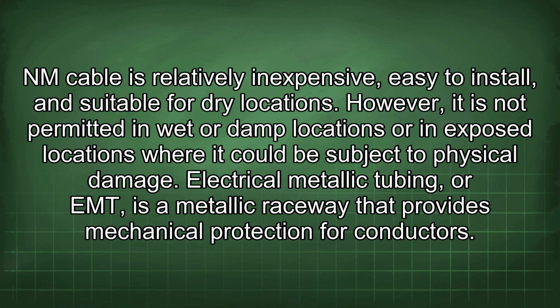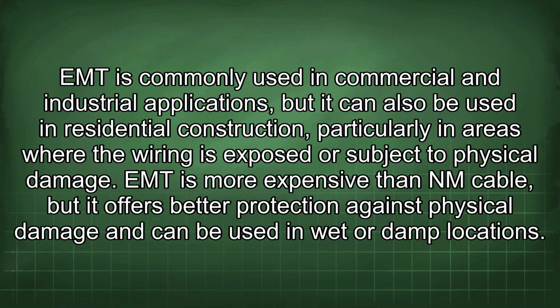Electrical metallic tubing, or EMT, is a metallic raceway that provides mechanical protection for conductors. EMT is commonly used in commercial and industrial applications, but it can also be used in residential construction, particularly in areas where the wiring is exposed or subject to physical damage. EMT is more expensive than NM cable, but it offers better protection against physical damage and can be used in